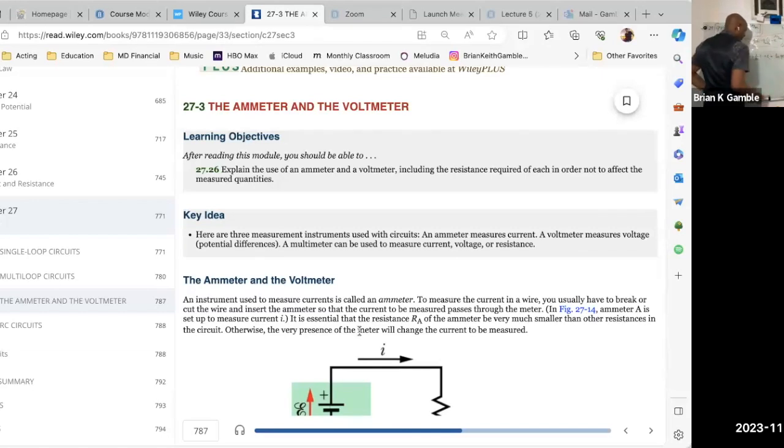Constant 1, constant 2. So we can go through and do that manipulation again, but in the end, you get this solution: Q of t is equal to basically EC times e to the minus t over RC. So for the discharging capacitor, that's the solution now as opposed to this. And the current is going to be the same. We just take the derivative of that, and you get the same solution, but just the minus sign is there.